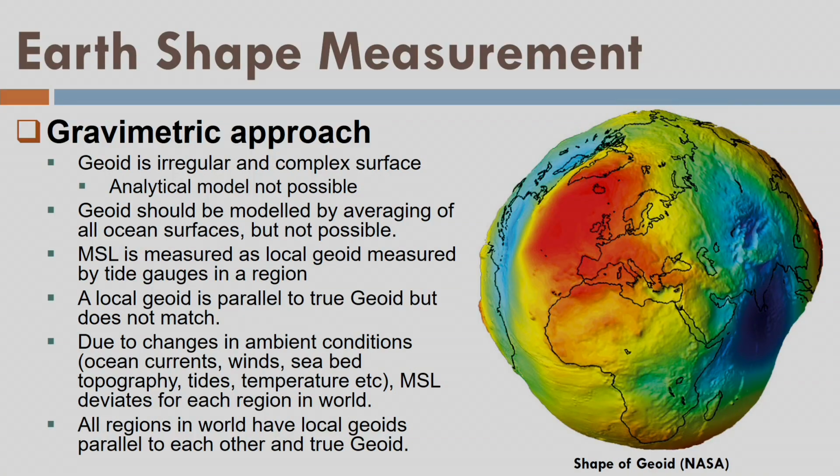Very difficult, because you can see there are two reasons. First of all, the geoid itself is very irregular in nature. Secondly, if you look, there is some sea surface and there is some land. On the right hand side of the screen there is a blue patch which is deeper, that is a deep sea. On the left hand side of this figure there is a blue patch, but it is still shallower. So now I have realized that there are some deep valleys in the sea, and in other seas there are shallow valleys, or no valley at all. I want to establish the MSL for one country, or a unique MSL.